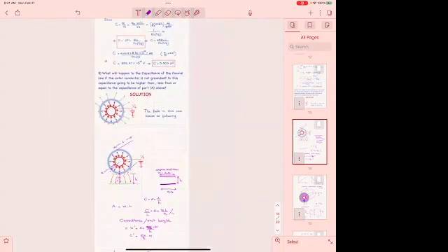You go and check the ground. And usually there are two ways of doing grounds in our measurements, either through the connectors. When we do probe measurements, we have probes that come with two grounds and a middle signal line, and they press down. The two grounds are for balancing, because if you only have one ground, it's not a balanced line, so it has problems. So, two grounds, one signal line. They press like this on your circuit.